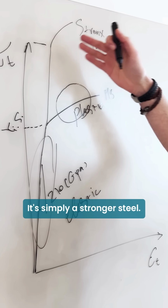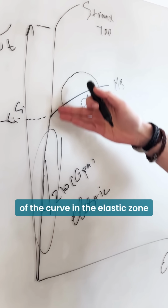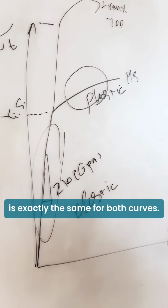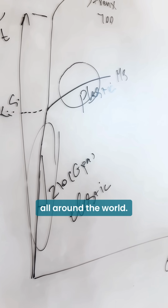It's simply a stronger steel. The similarity is that the slope of the curve in the elastic zone is exactly the same for both curves. It's actually exactly the same for all sorts of steel all around the world.